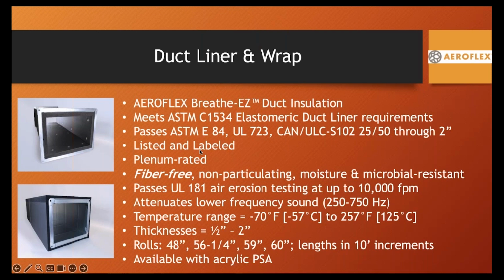Breathe-EZ is fiber-free, non-particulating, moisture and microbial resistant. It does pass the UL air erosion test up to 10,000 feet per minute. It attenuates unwanted noise at the lower frequencies, and we're going to address that in the next slide. Thicknesses available range from 1/2 inch to 2 inches thick, rolls in 48 to 60 inch widths, and lengths are available in 10-foot increments to be optimized for water jet machines. And all sizes are also available with an acrylic PSA or peel and stick back.